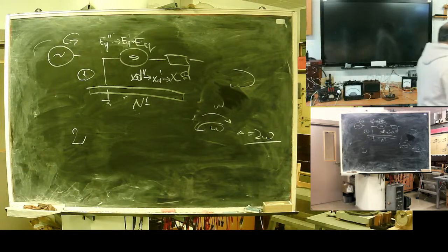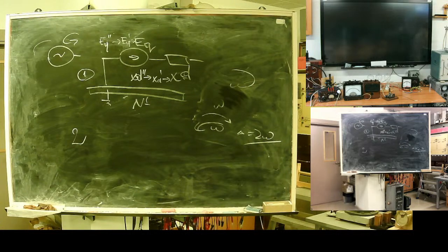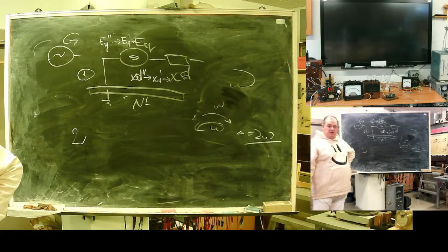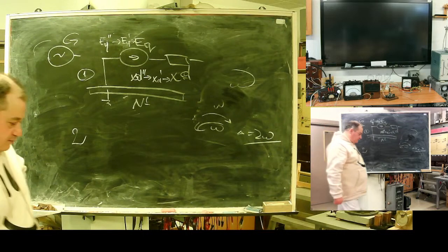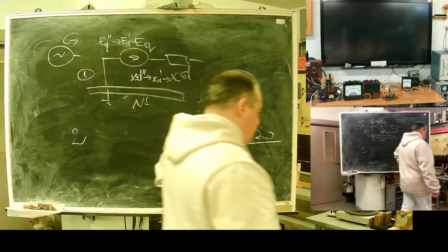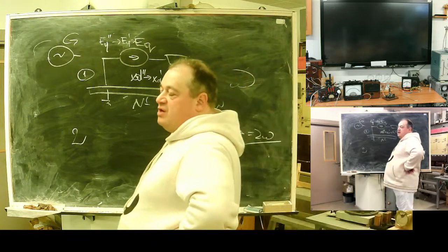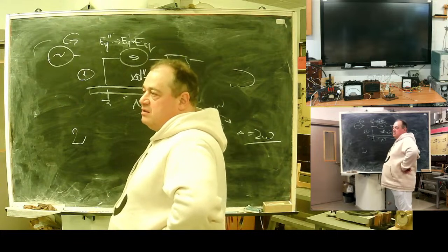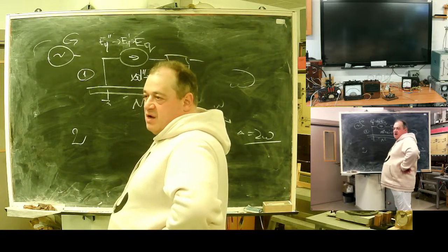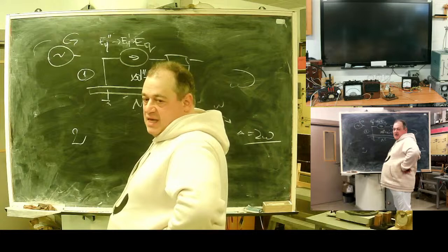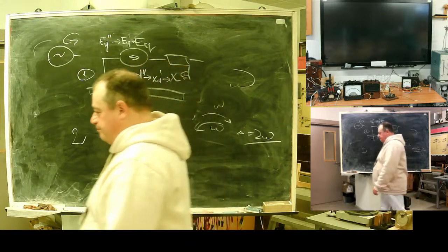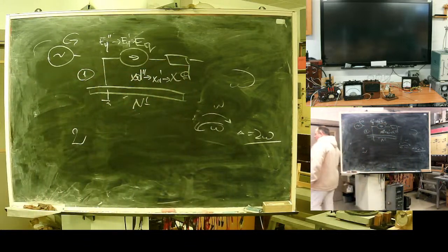For hydro generators, with this short circuit winding in the surface of poles, so for machines with damping winding, this poses little danger because negative sequence current will close in these short circuit rings.